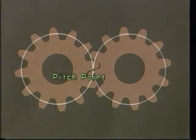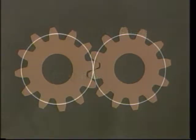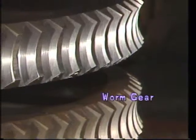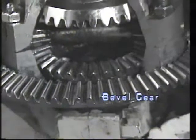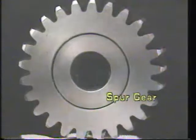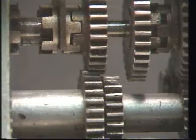The imaginary circle passing through the pitch point is the pitch circle. This is the reference circle of the gear. Gears are normally of different kinds. The simpler and more familiar form of gear is the spur gear. It is used to transmit motion exclusively between shafts parallel to each other.